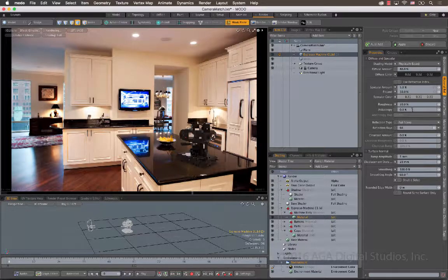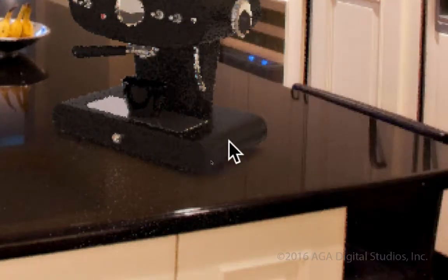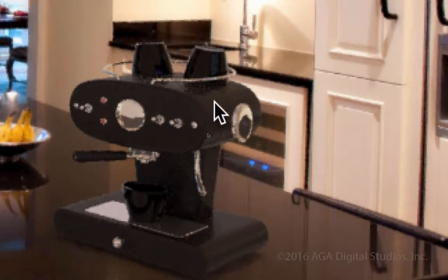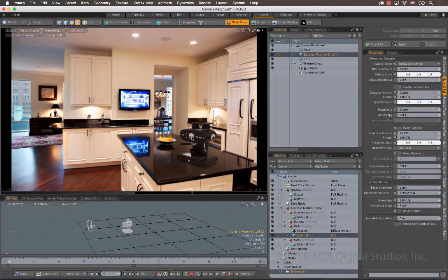Okay. And from there, the roughness, I think maybe I'm going to bring that up to about 50. And then I'm going to bring my diffuse down maybe to about 65. And what that's going to do is take a little less light from the scene. And from here, we could put a bit of a clear coat on too, depending on how shiny you want that. But now you can see that it's not quite so clean and shiny. It's a little bit rougher surface. All right, now let's do the same just for the metal real quick, and then we'll move on.